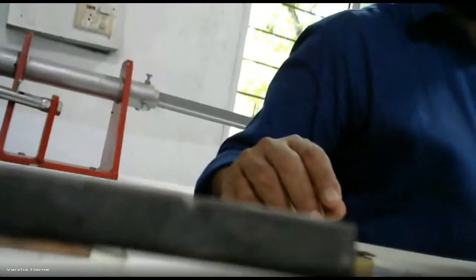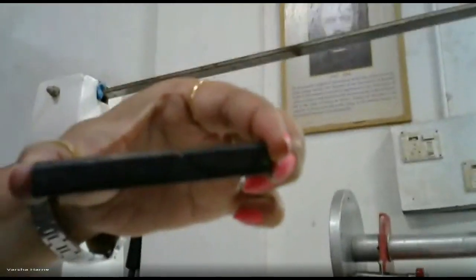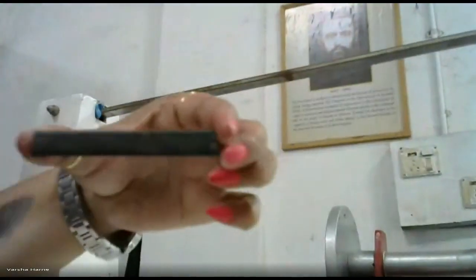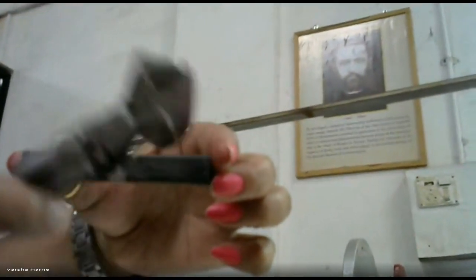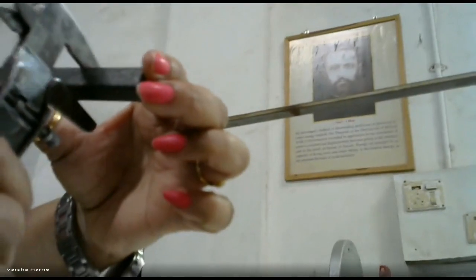different types of specimen. Now see here, these are our different specimens which are required. One is for the mild steel, isn't it? If you see here, this is our mild steel bar, and there is one groove, which is important, to calculate the area of that notch. Now see here, this is our specimen. Do you see this? By using the vernier caliper, you have to measure the dimensions, that is the length and depth. For the depth, you have to consider below that notch.